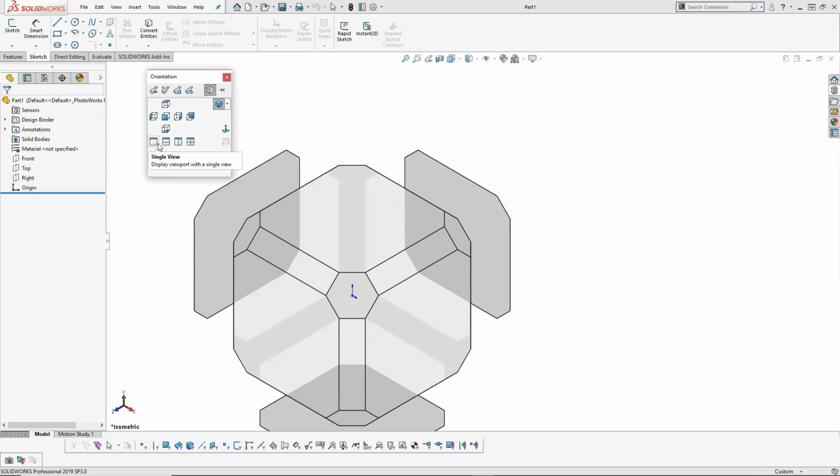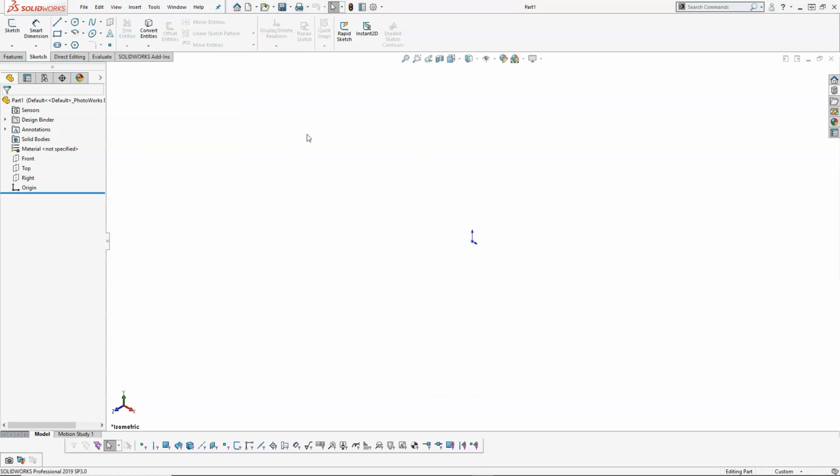It's being able to split the screen. We have single view, 2 view horizontal, 2 view vertical, and then the 4 views. Occasionally that's handy, but not so much. And then if you don't want to see the view selector, the control spacebar toggles it on and off. Updating standard views, reset standard views. We can manipulate those a little bit, but I would recommend holding off on that.